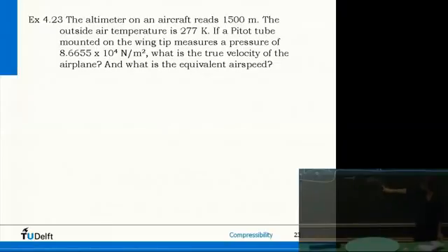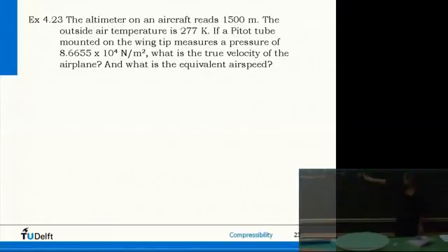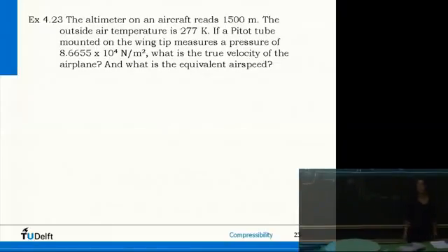So the speed goes in, and then the tube fills itself with air. So what is the pressure that you measure here? Stagnation pressure, indeed, because it fills itself and then it doesn't flow through. So if you put this tube into the flow, this pitot tube measures the stagnation pressure, or total pressure, there where the speed is 0.